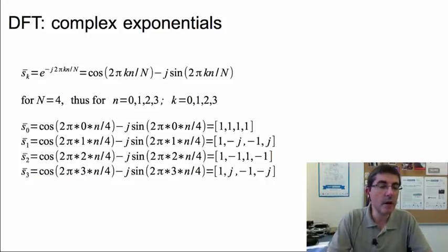So one of these complex sine waves is S of K, in which using Euler's identity, we can express it as a complex exponential e to the minus j 2 pi k n divided by capital N, and this is equal to the cosine of the same value minus j sine of this same frequency, so the real and imaginary part of this complex exponential.